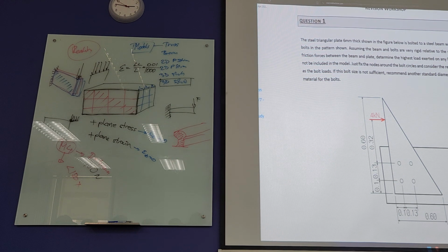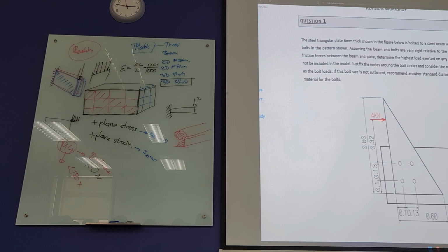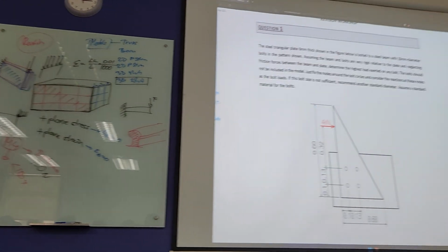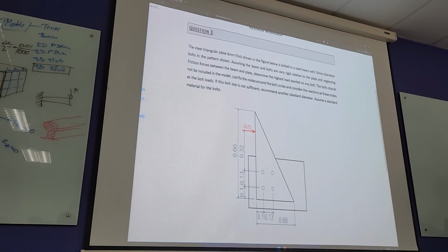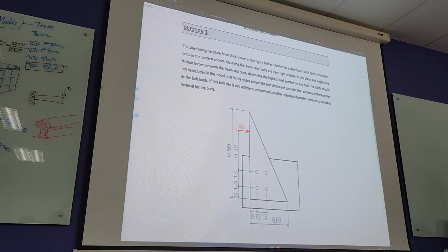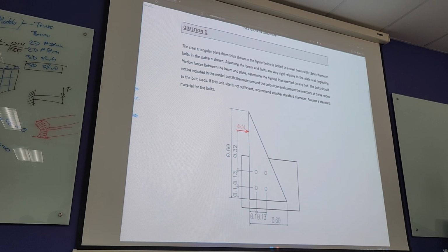So now you need to input the load. You won't have any load there, so you need to put a partition. Here is correct. You go to the last, the middle. Up one more. Yeah, you press this one, then press on the face. Okay, so now you can draw. So you just draw the distance where the load is. Just draw a line across.